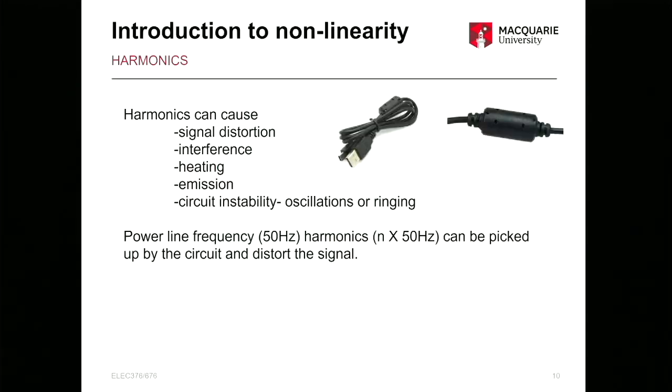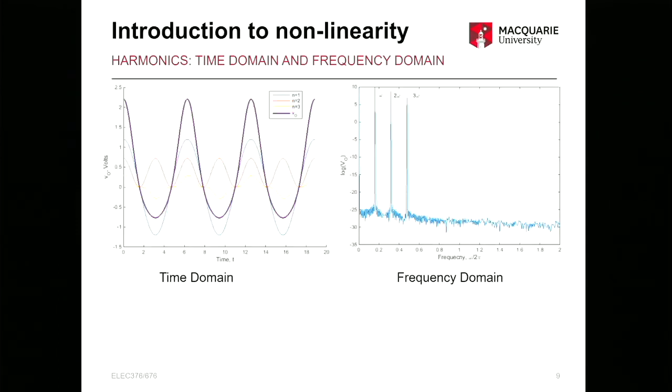So you saw here we have 3 components. If you just had the time domain signal, you could do nothing with that, okay? But when you look at the frequency domain, you know that you have 3 frequency components, and if you want to find the fractional distortion of the third order, or HD3, you would look at the amplitude of the 3 omega divided by the amplitude of omega, which would be 6 divided by 10.